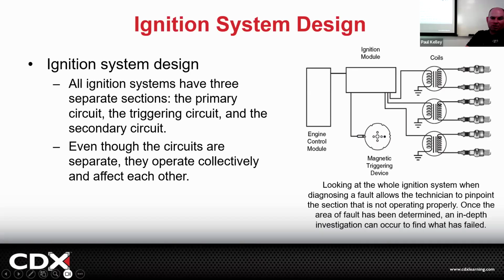Yeah, it's in the distributor on the older system, but on this one, I can't tell if it's a distributor type or not. It looks like it could be, but either way, this is what's going to tell you where the engine's speed and location is. It could be a crank or cam position. On an old school car, they didn't exactly have crank and cam. They had just an ignition pickup, and the pickup would pick up where the engine was and then send a little signal.